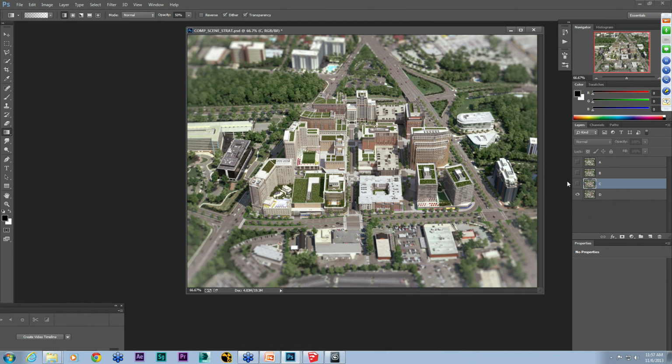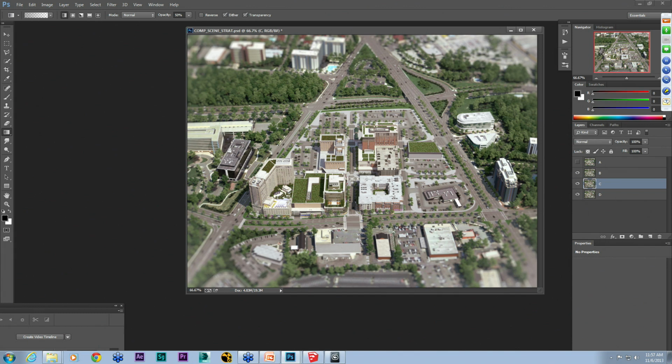So we needed to figure out a way that we could have multiple artists work on this at the same time across a bunch of different files. And we had to manage things like, once you switch the phase, how do you make sure that things that are on one phase and on the next don't change? So you want to make sure that the trees that are in one phase, and don't actually change in the next, have to be in the same position between the different phases. And then once we started rendering this, we ran into all kinds of network issues because we started using layers of XREFs, and we had to change our strategy then for the final product.